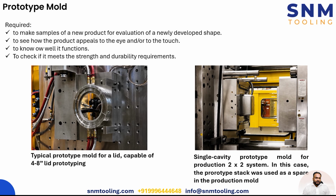So there can be different ways through which we can decrease the cost of the mold. For example, the ejector system can be quite simple, just making use of air directed towards the edge of the product for it to eject manually. No use of advanced ejector system, or we can simply make use of ejector pins for manually pushing them so that the product can be ejected.